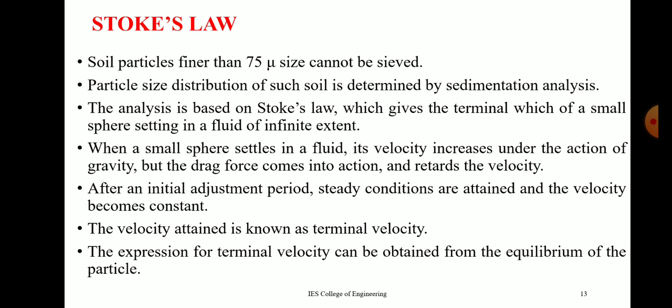Stokes law. Soil particles finer than 75 micron size cannot be sieved. Particle size distribution of such a soil is determined by sedimentation analysis. The analysis is based on Stokes law, which gives the terminal velocity of a small sphere settling in a fluid of infinite extent.